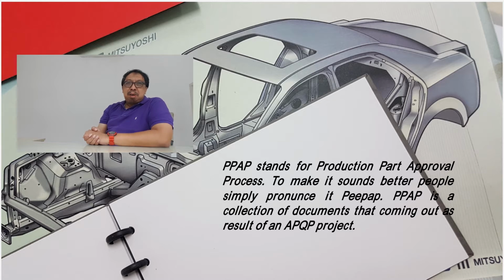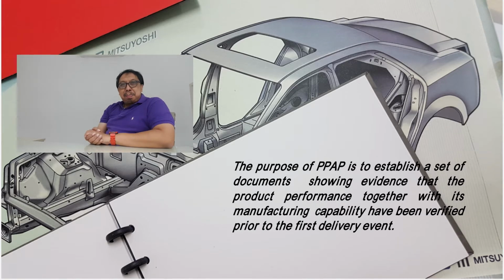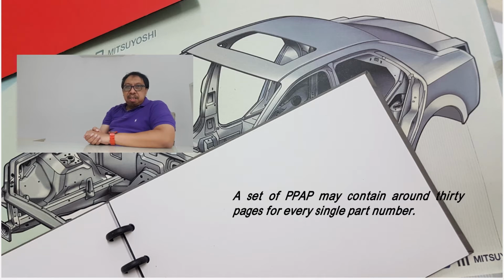PPAP stands for Production Part Approval Process. To make it sound better, people simply pronounce it PPAP. PPAP is a collection of documents that come out as a result of an APQP project. We can only find PPAP in automotive industries. However, they do have a similar documentation system in aeronautical, military, and nuclear industries. The purpose of PPAP is to establish a set of documents showing evidence that the product performance, together with its manufacturing capability, have been verified prior to the first delivery event. A set of PPAP may contain around 30 pages for every single part number.